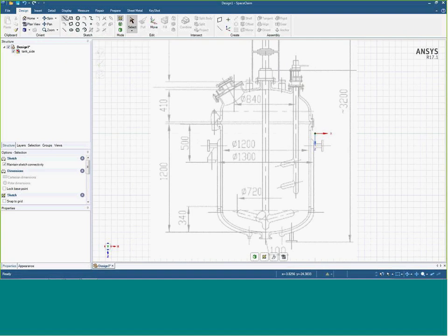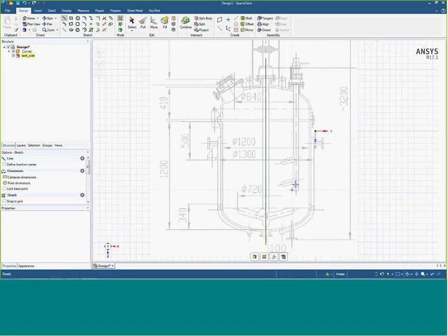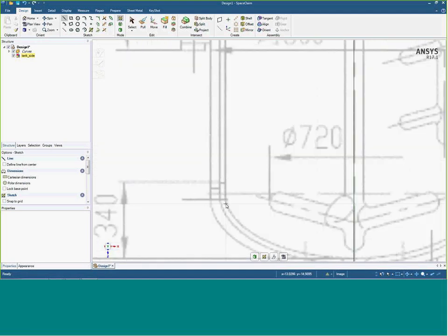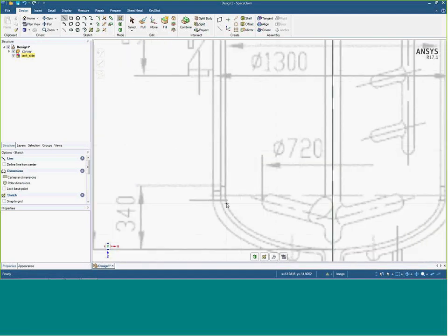So I'll start off with under the sketch tools here, just left-click and then grab a line. So I'm just going to left-click once to start a line, left-click again to end the line to put a center line down the part. And just roughly sketching this. You probably want to scale everything to be the right size initially too, but you could also do it at the very end. That way the size of this actually corresponds to the dimensions in the picture.